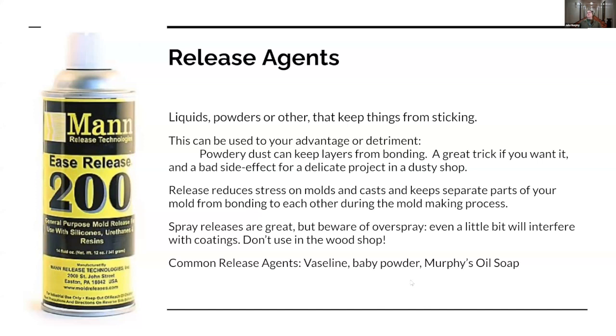Baby powder is good also for creating a dust that will keep things from sticking. However, one thing I will say: do not ever spray a release in a wood shop, because if it gets on someone's projects, they will not be able to finish their project. The release will keep their varnish or whatever from sticking. You may think, oh, I can just duck in here to spray it. Do not do that. That is mean.